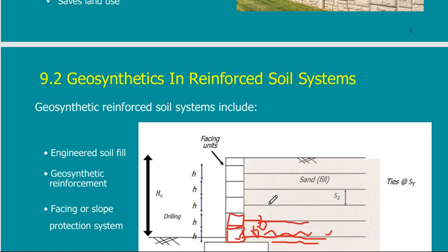But to be honest, of course, this is a very good system, but it is applicable for new construction. You cannot tell me to use it to support something that is standing now. If you have piles of soil that are in place and you want to construct a wall to prevent them from falling, you cannot use this system, because this system necessitates that you remove and put your wall and then backfill again.